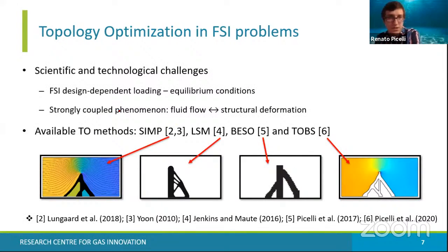So that's the first scientific and technological challenge: how to deal with the FSI design-dependent loads, how to impose the equilibrium conditions properly, and which phenomenon we want to look at, because there are several types of interaction between a fluid flow and structure deformation. It can be small displacements, large displacements, etc., laminar flow or not.